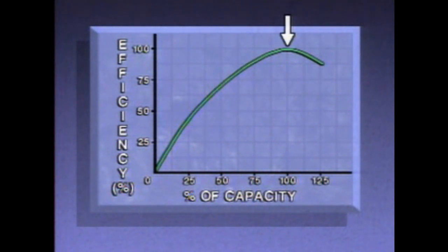The point of maximum efficiency is the point where the pump provides the maximum flow for the least amount of power. If the other plant concerns, such as safety and production, allow it, this is the most desirable flow rate at which to operate this pump.